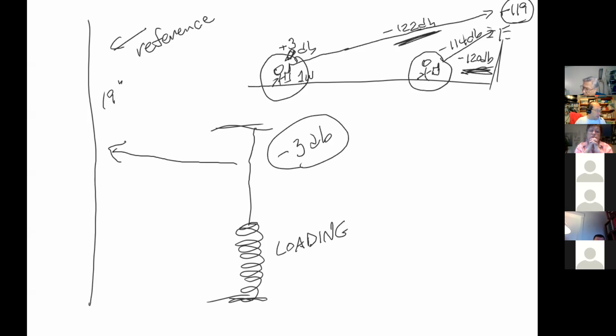Okay. So you mean you make a short antenna very long, or did you mean...? No, you make a long antenna very short by coiling it up. Oh, okay. So what you're saying, Scott, is that you could have the exact same length antenna. It's just in this diagram, where you're at the further away spot, if it's coiled up, you've got that impedance and that causes you to not be heard. But if you had the straight antenna at the exact same location and it's still 19 inches, then you don't have the impedance with the straight antenna and you can be heard.